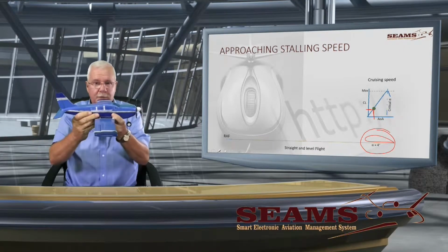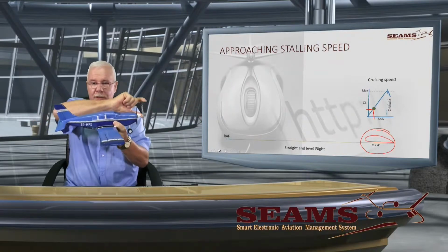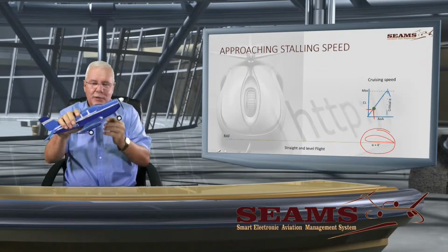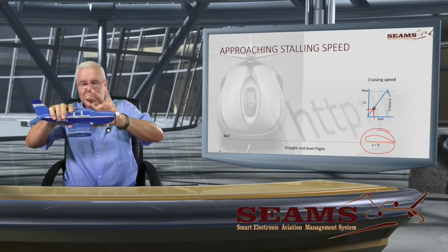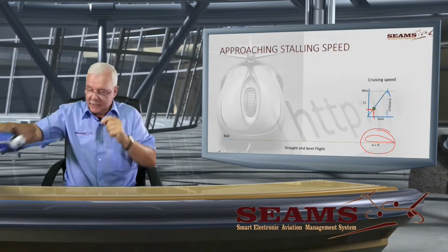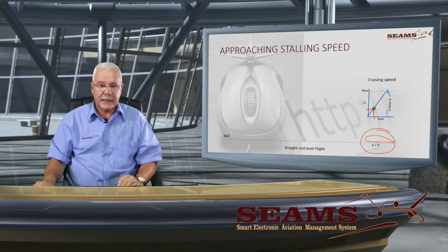So when it's flying at the optimum angle of attack, the best lift-drag ratio of 4 degrees, then the longitudinal axis won't be inclined. There will be less profile drag, because you're not going to fly like this. You're going to fly nicely, and the frontal area of the aircraft is going to be less. All right. But we'll get to that one also a little bit later.